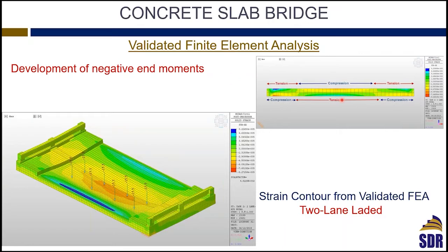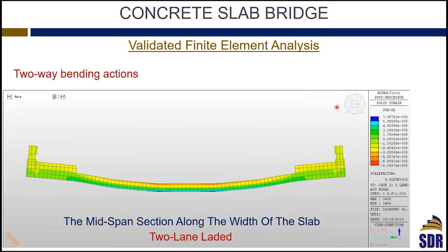So for example, if you assume this is simply supported, your positive moment at midspan, let's say, is 100 kip feet. When you start doing this negative moment, you will have a negative of, let's say, negative 40, and this 100 will drop to positive 60. So when you do your load rating now, you are not using the 100 kip feet to determine the rating factor. However, you should be using less positive moment, which is 60, given the numbers that I'm using.